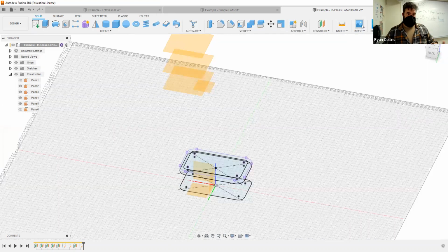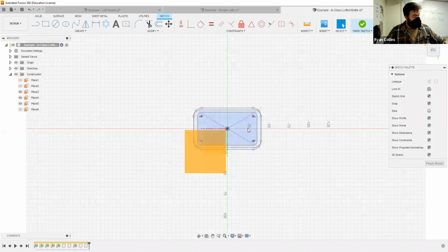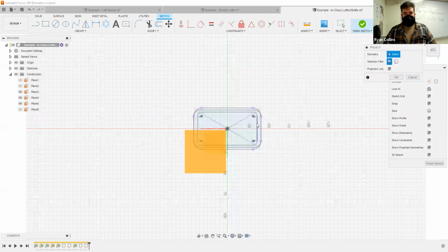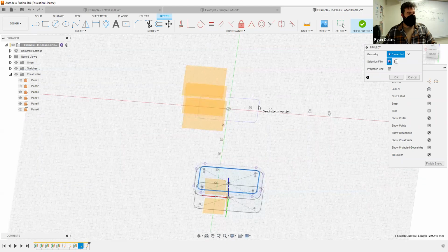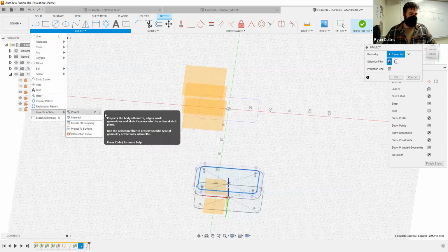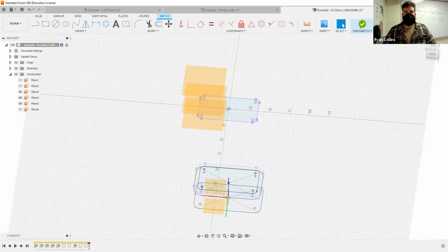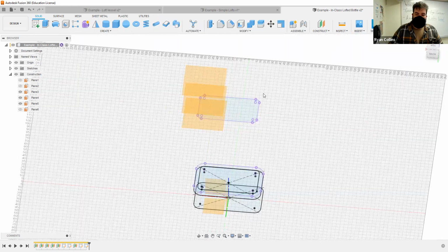And this is the part that gets just really tedious. New sketch, way up here. Cool. Now, since this bottle is essentially a straight line from one to the next, why draw another one entirely? I can take a projection of that sketch, duplicate it up here just by pressing P, or again, I use the drop down, go to project, include, project. That's where the tool is. Hit OK. Bam, done. There's my sketch right there. I don't need to add anything else to it. Excellent. All right.